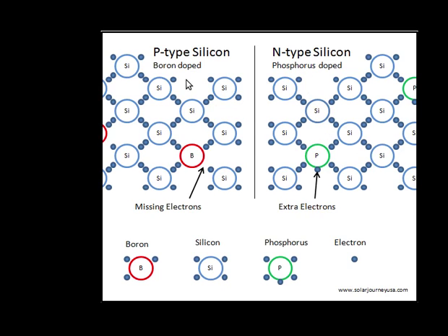And this doped silicon can be a resistor or a conductor. So these can conduct electricity. And the resistance level depends on the level of doping and also the type of dopant. Electrons conduct charge more easily than holes do. So electrons are a charge carrier that move more easily than holes.